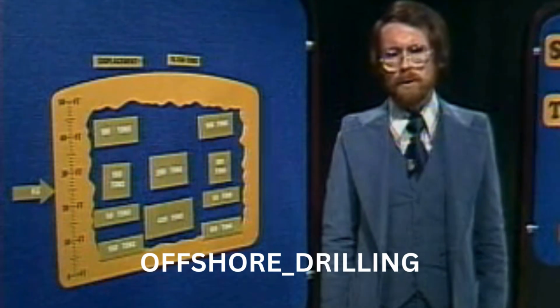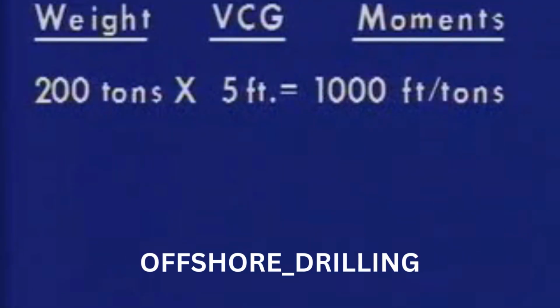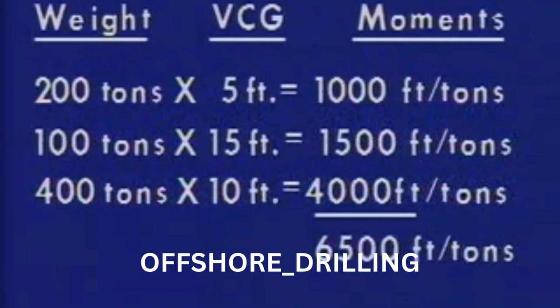The moments for the removed cargo are calculated like this: 200 tons times 5 feet, or 1,000 foot-tons. 100 tons times 15 feet, or 1,500 foot-tons. 400 tons times 10 feet, or 4,000 foot-tons. The total moments for the removed cargo are 6,500 foot-tons.